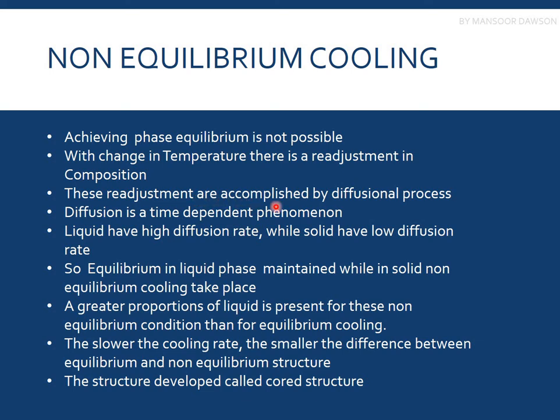These readjustments are accompanied by diffusional process. As I discussed earlier, there is no time for the heat to diffuse out from the inside. So diffusion is a time-dependent process. It takes time. Again, liquids have high diffusion rates, while solids have low diffusion rates. Since the diffusion rate of solids is very low, we have to give a lot of time in order to get an equilibrium phase. So in equilibrium, the liquid phase is maintained while in solid, non-equilibrium cooling takes place.